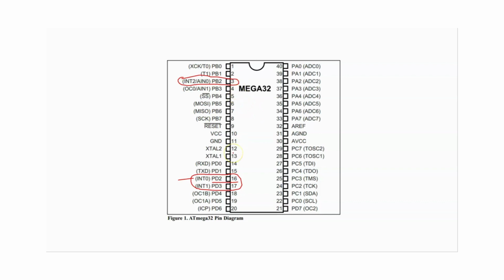So these three external interrupts can be used, whereas the timer interrupts are related to timers, which are also three timers in this microcontroller. However, we can use more than one interrupt related to each timer. So we will discuss the overall interrupts in the next slides.